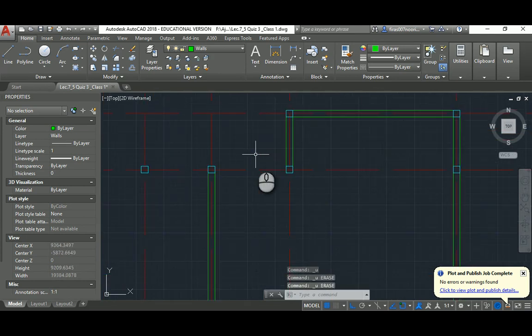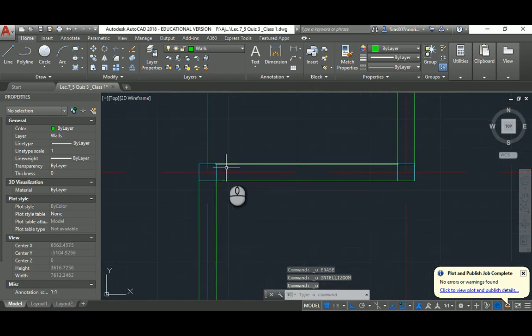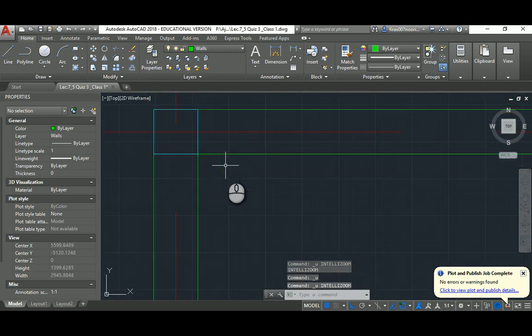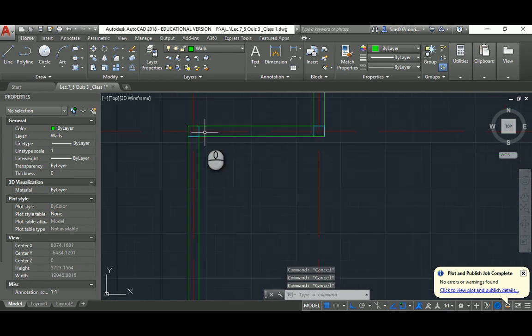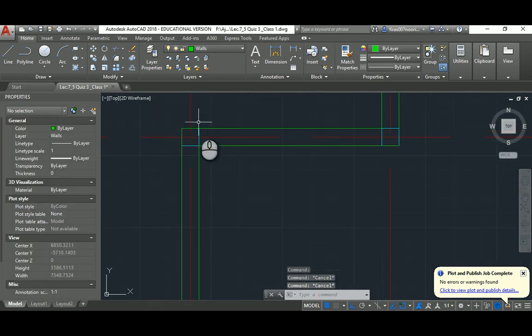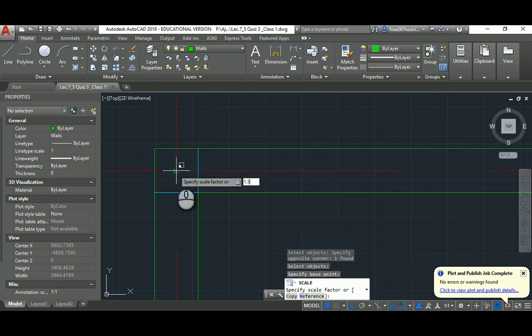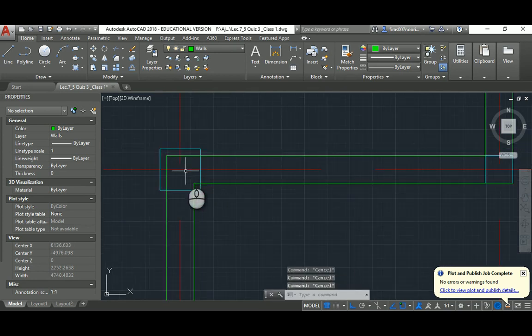And by the way, again, that's the columns. If they are actually of the same thickness as the wall, that's how we draw. If we have a bigger case, if the column were actually like that, that's another issue. So you have to start the walls from the outer edge. You must, in this case, start the walls from the outer edge.